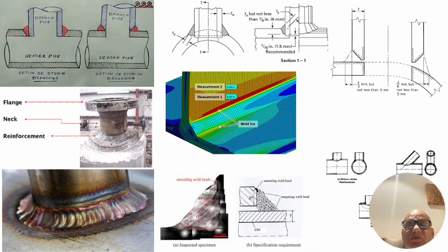So coming back to our nozzle weld, the number of weld lines or the number of passes in this area may be lower than the number of passes which are required to be built here, because our fillet is going to be measured from this height, as you see here, where we have to get the throat. Here, achieving a throat in this direction of the weld is easy, in this direction it becomes a little difficult. So the number of passes is going to vary.